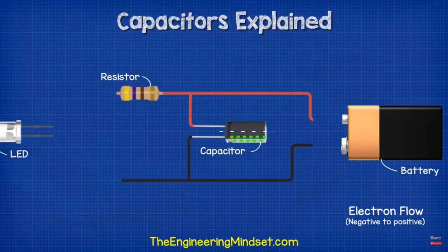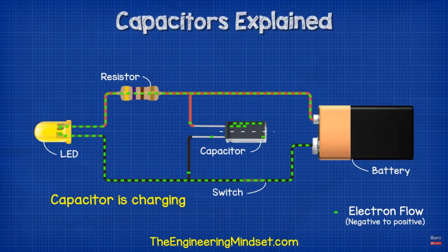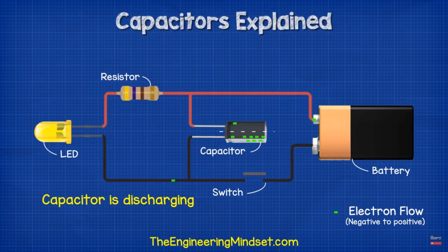If we then place a small lamp into the circuit, a path now exists for the electrons to flow and reach the opposite side. So the electrons will flow through the lamp, powering it, and the electrons will reach the other side of the capacitor. This will only last a short duration though until the buildup of electrons equalizes on each side. Then the voltage is 0, so there is no pushing force and no electrons will flow. Once we connect the battery again, the capacitor will begin to charge. This allows us to interrupt the power supply and the capacitor will provide power during these interruptions.